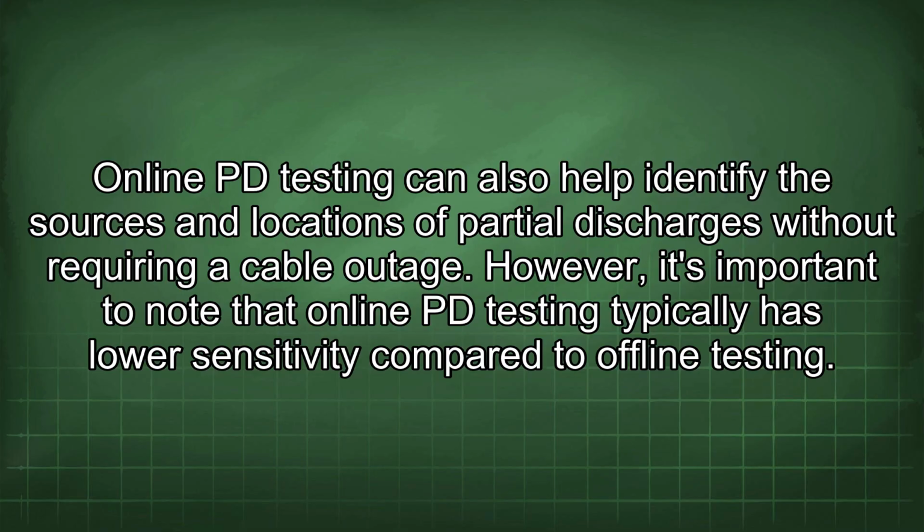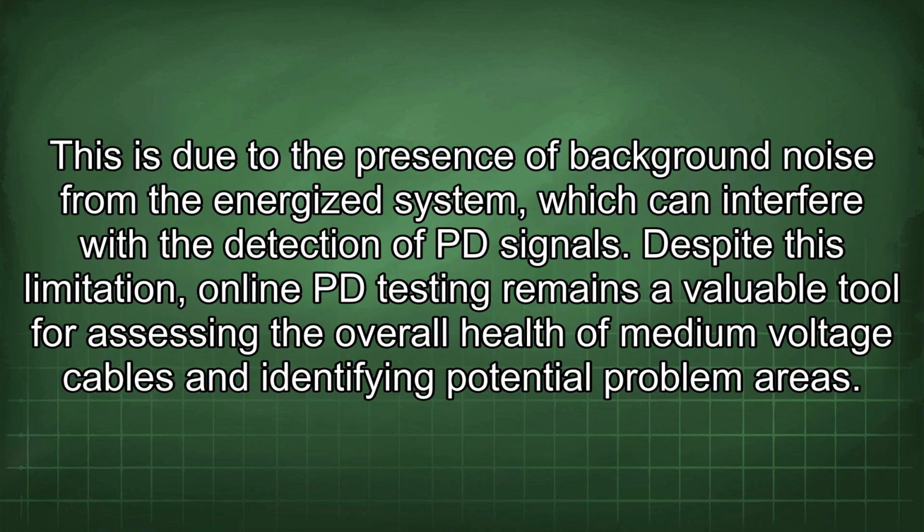However, it's important to note that online PD testing typically has lower sensitivity compared to offline testing. This is due to the presence of background noise from the energized system, which can interfere with the detection of PD signals. Despite this limitation, online PD testing remains a valuable tool for assessing the overall health of medium voltage cables and identifying potential problem areas.